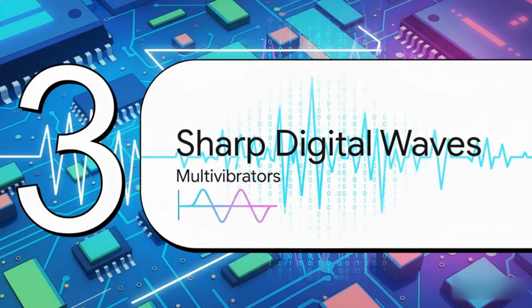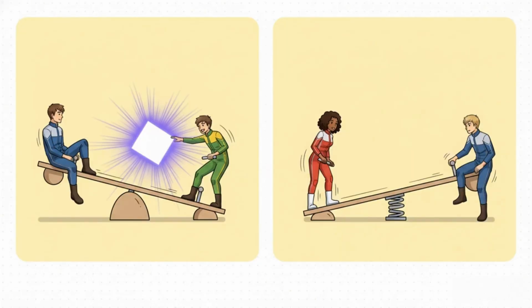All right, so we've covered the smooth, flowing world of analog waves. Now let's slam on the brakes and jump into the digital world, the world of sharp edges and absolute states. It's either on or it's off. And this is the domain of a family of circuits called multivibrators. They were born to do one thing: flip back and forth. The secret to telling these guys apart is their stability, or you could say how comfortable they are. A bistable circuit is totally happy sitting in one of two states, which, you guessed it, makes it a perfect little memory switch. Then you have the astable circuit. It's never happy. It has 0 stable states, so it just restlessly flips back and forth, forever.